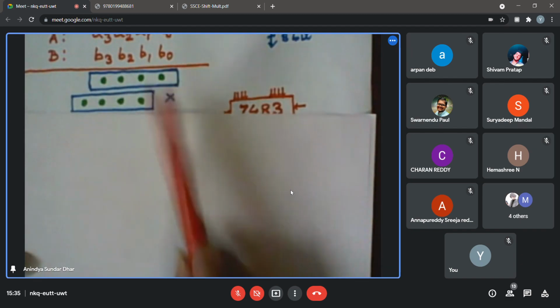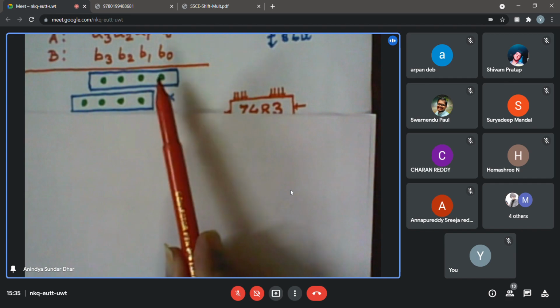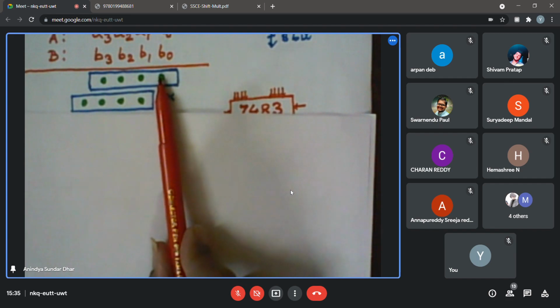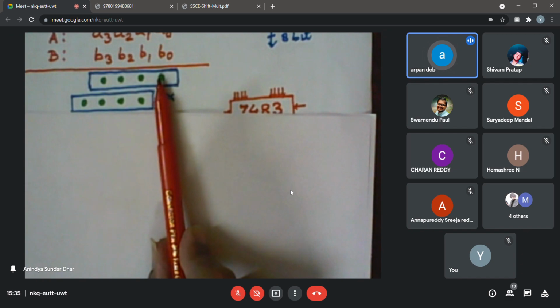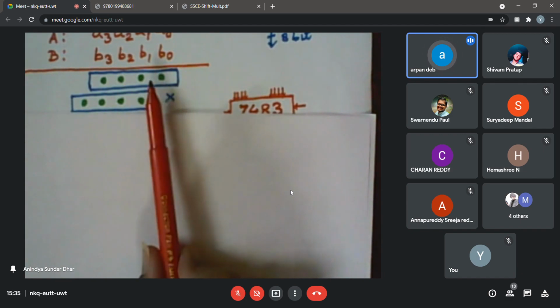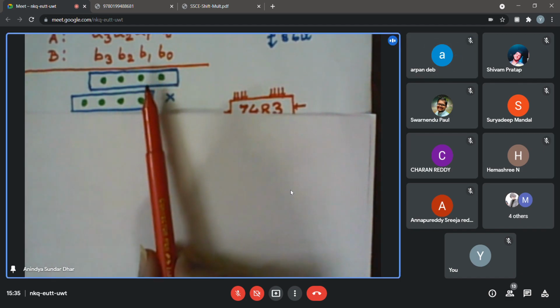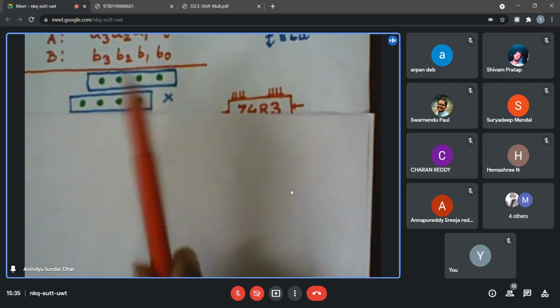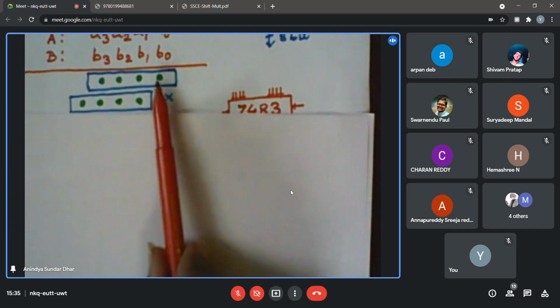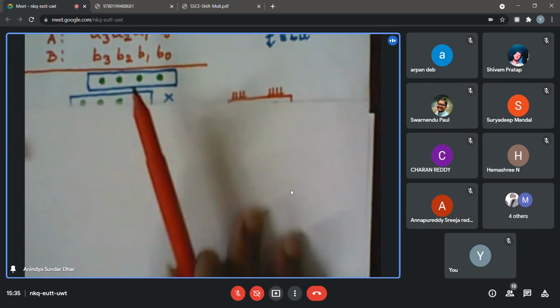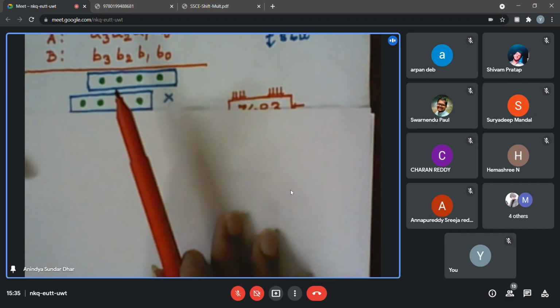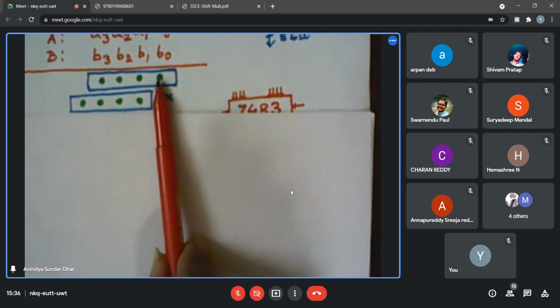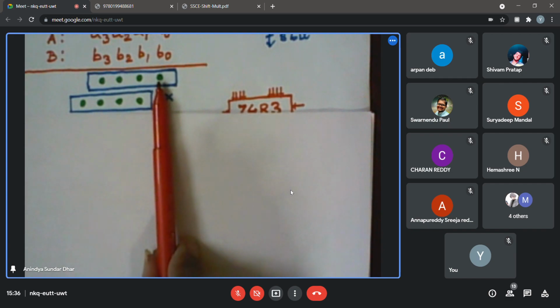Okay. So then do you feel in my 7483, I should fit this bit? No, I think the first 3 bits of the first partial product and the last 3 bits of the second partial product should be added only, and the other 2 bits will be constant. Right. That is the part where I said you require to apply your thought process. But here there is some hint. When I have added this one with 0, think about that one, because the next operation, as is apparent, I do not need to put this one through the register, but still I cannot forget that bit as well, right? I need to remember that.